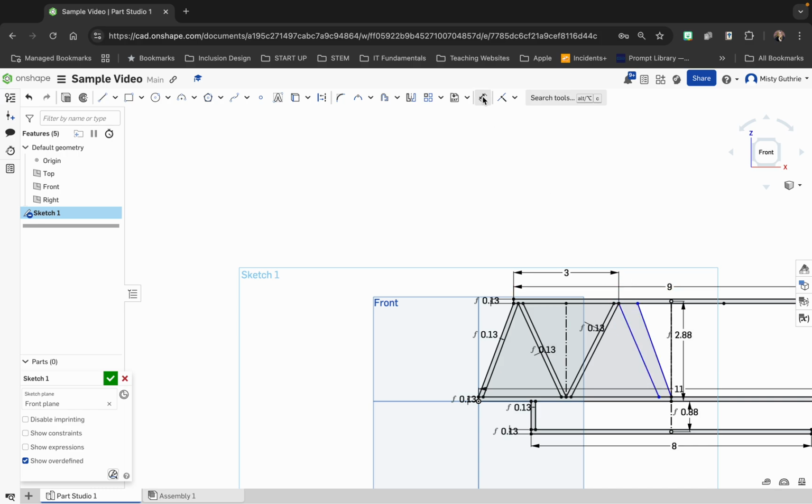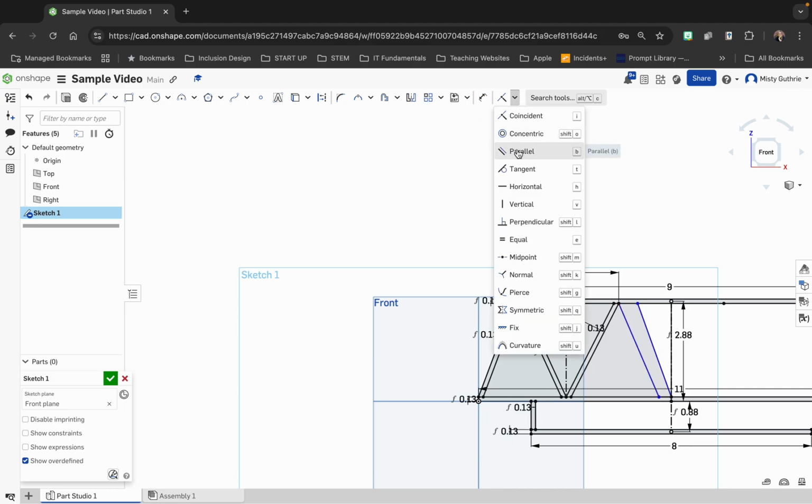So if you go to dimension across two lines that are not parallel, you will see something that looks like this. If you see degrees, like that little circle up there by the 5/7, that means that you need to hit escape and go up here to your tools. You may need to pull down the menu if you don't see it. Find this tool that makes two lines parallel. There's a lot of other great tools in here as well. You can make lines horizontal, vertical, perpendicular.